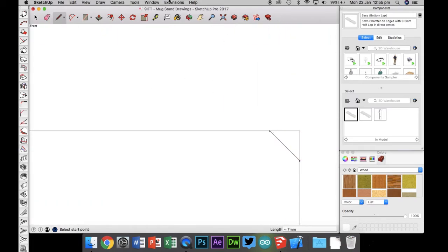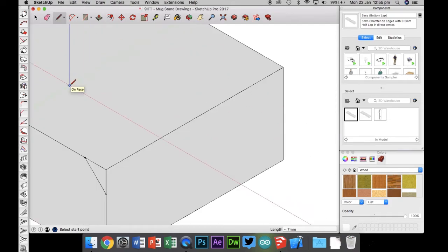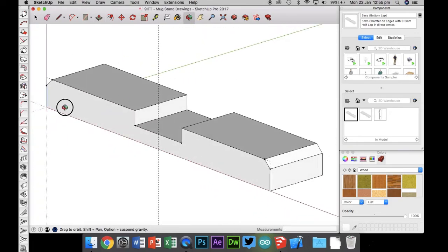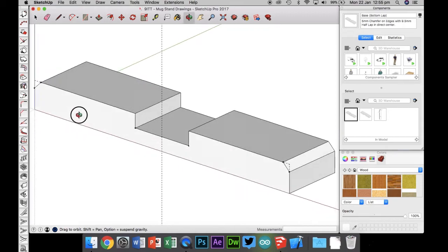Click to click. Now if we go back to our isometric view, fit our project in our screen, you'll see that we've got those triangles now. Again, using the push-pull tool, just need to drag those sections away. And now if we rotate around, we're pretty much done with part C. The only thing that we need to do, we're going to get rid of our measuring lines, so click and delete, wait for them to highlight blue. Measuring lines can sometimes get a little bit in the way.